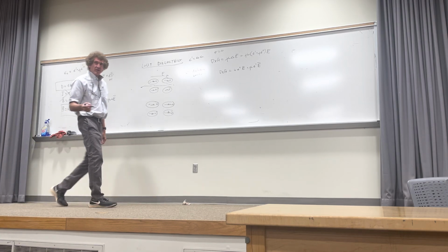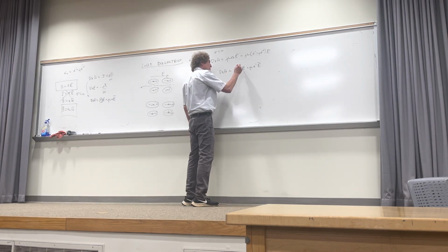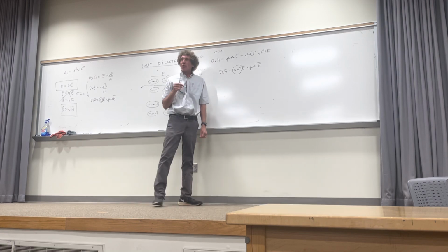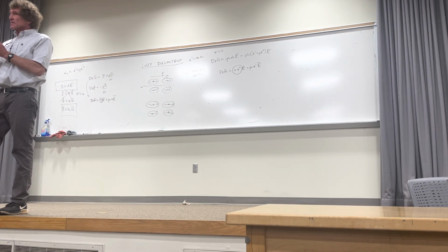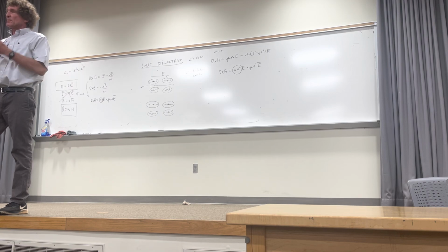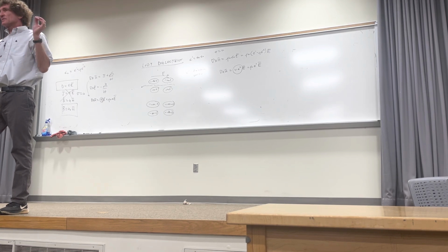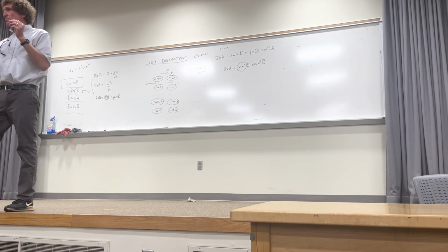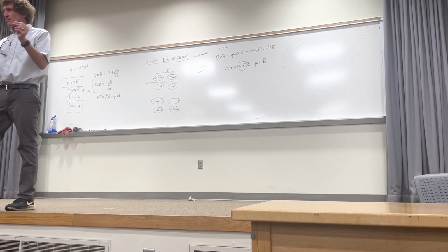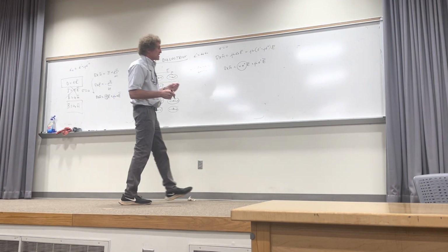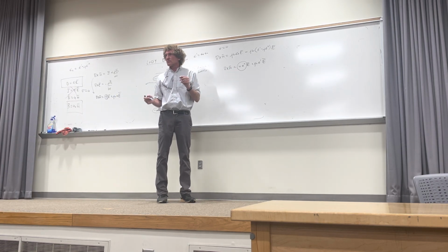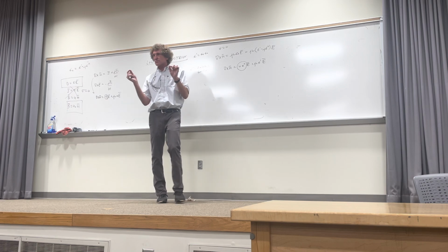All right, look over here. This term is like sigma, only now we're not talking about a sigma that allows electrons to flow in a continual fashion through the lattice. This is a loss term that has to do with bound charges and the loss involved at different frequencies. And by the way, one thing that's very important to see is this loss is proportional to frequency, and that's absolutely true. And here's why.